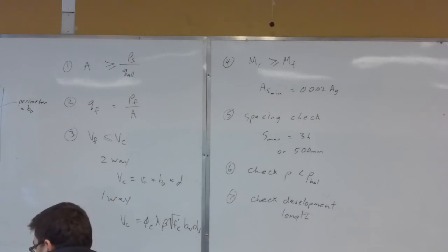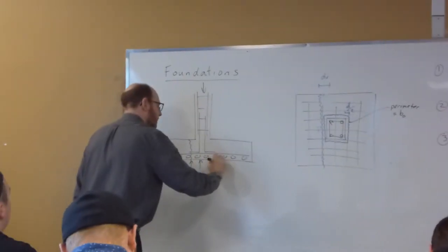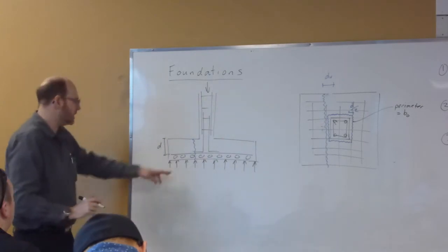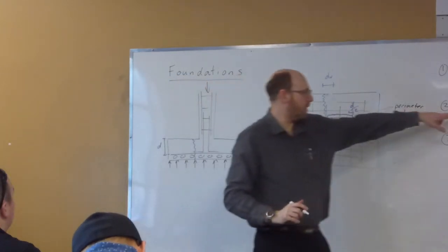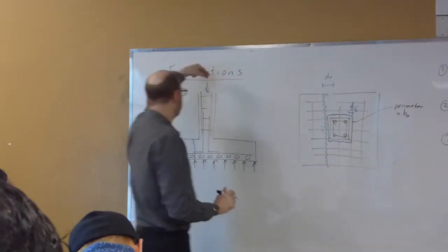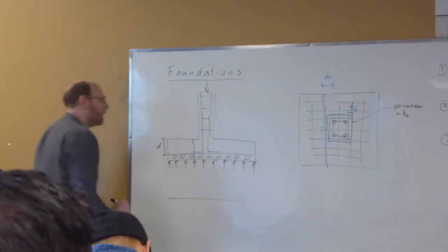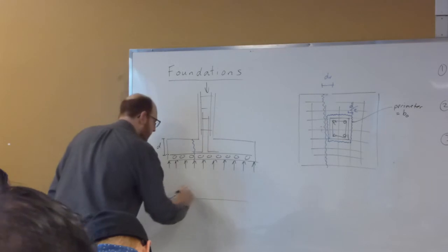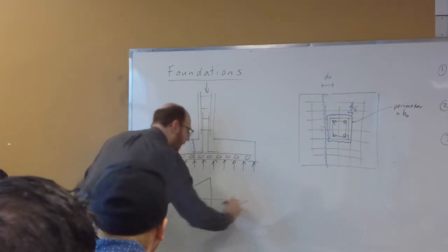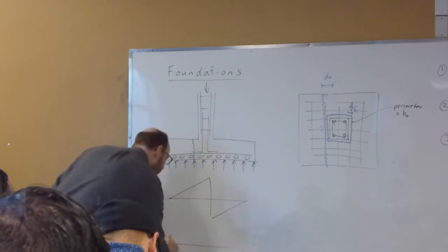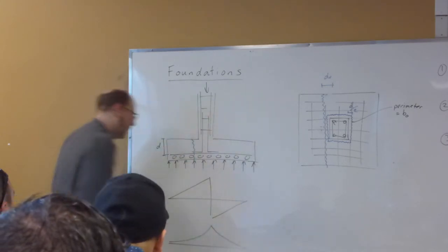We've got an axial load coming down here, and I have a UDL that is resistant based off of this. So this is that QF that we calculate from here. I have a PF coming down here, and a QF coming up. So our shear diagram has something that looks like that, and then our moment diagram will look something like that.